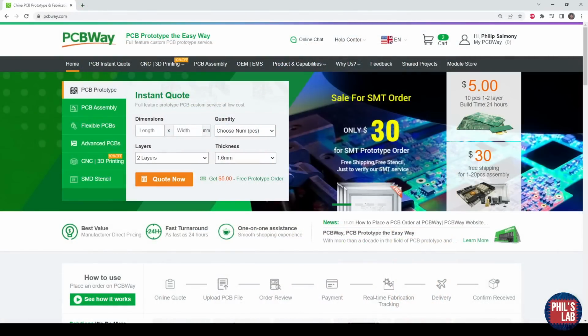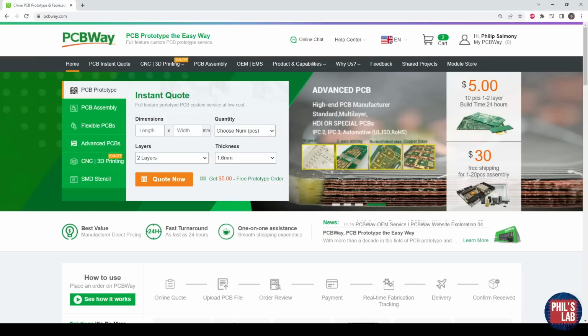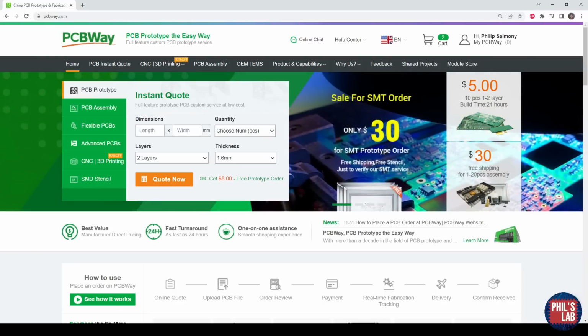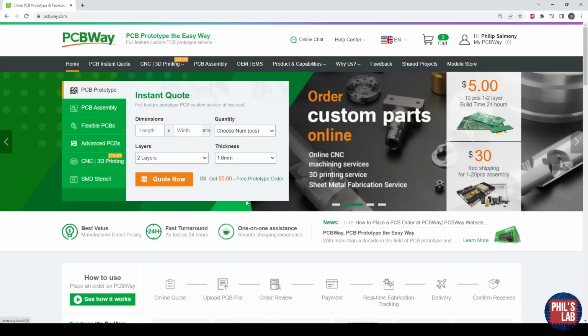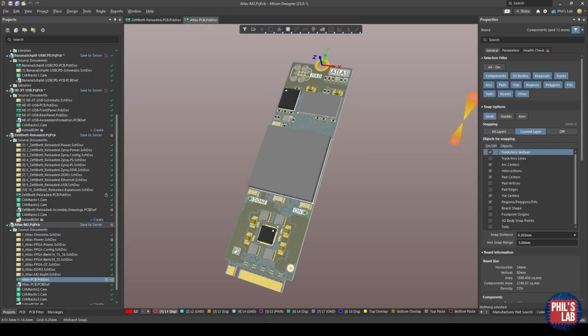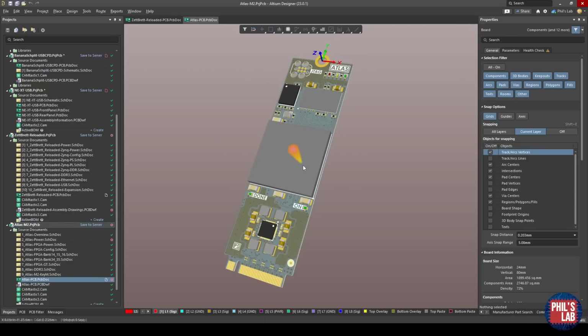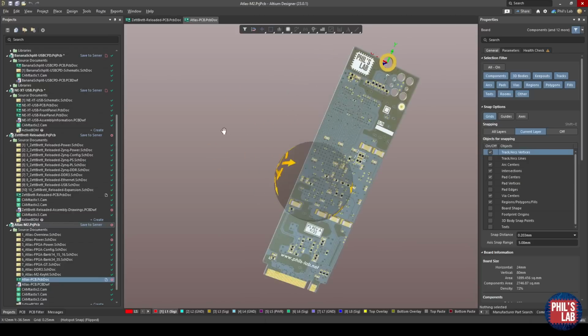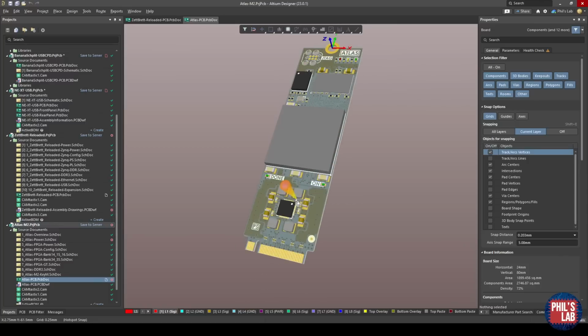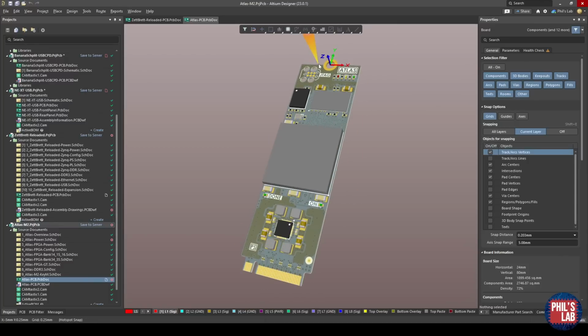As I said at the beginning of this video, the PCBs I have made for this channel are manufactured and assembled by PCBWay, and I'd also like to guide you through the process when you'd like to get your PCBs manufactured and assembled by them, what files you need, how you communicate with your manufacturer of choice. I'd like to guide you through this process looking at two examples. One is this FPGA hardware accelerator board, which is an M.2 card featuring a Xilinx Artix-7 FPGA, some DDR memory, with double-sided assembly, some special requirements, for example this edge connector, some edge plating and so on.